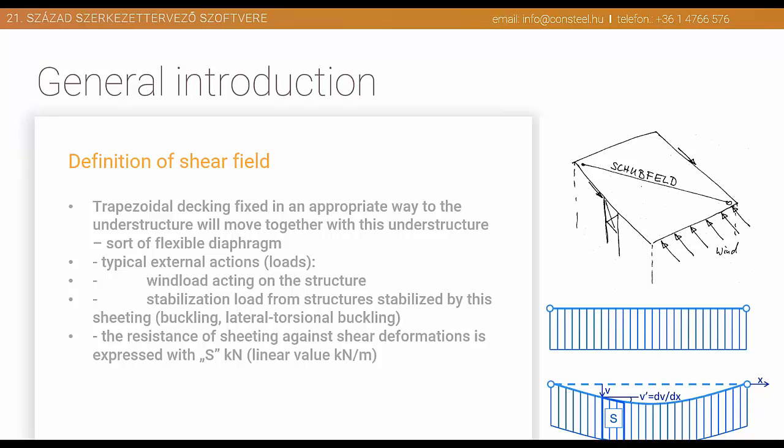Now, if I calculate an internal frame independent from the fact that the roof would anyway connect it somehow to the much more rigid sidewalls, then I will come to the conclusion that my structure has a relatively high period of vibration. As a consequence of that, my seismic force will be relatively small.